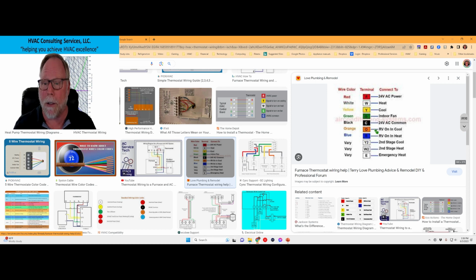If you have a thermostat, such as this example here on the right, and it's got both an O and a B, you're going to need to go into the thermostat configuration and tell it whether it energizes in heating or energizes in cooling. Or they'll have a dip switch on the back of it. You may have to turn it over and flip that dip switch between O and B. You need to know your unit and find out whether or not it energizes a reversing valve in cooling, so it uses O, or for heating, it uses B. And again, this is heat pump thermostats only.